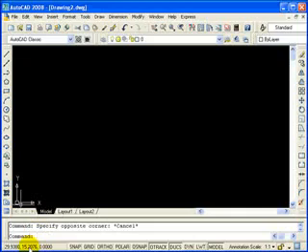At the very bottom, on the left-hand side, you'll see your status bar, and in the bottom left-hand corner of your status bar you'll see your coordinates. That's the coordinates of where the crosshairs are in the Cartesian coordinate workspace, which we'll touch on a little bit later. There's some options here for turning on some of the AutoCAD options as you're drawing. You can click on these as you're working. O-snaps, ortho, and things like that. We'll get into some of these other options as well.